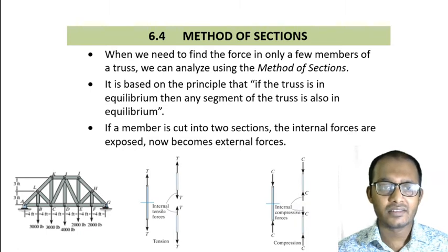So in these cases, it's very wise and beneficial to apply the method of sections. It reduces the workload and simplifies the solutions. So when we need to find the force in only a few members of a truss, we can analyze using this method of sections.